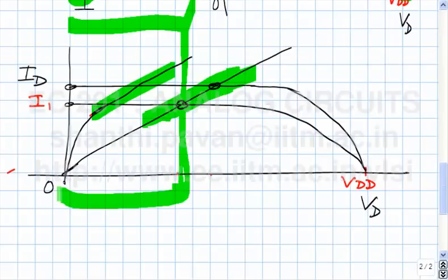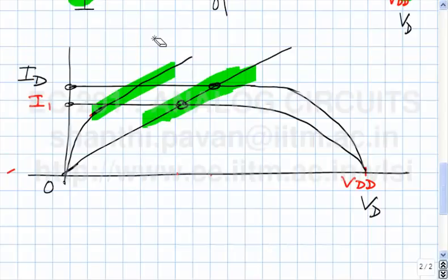And then you say, well, unfortunately, if this characteristic remained a straight line, then that element there would neither be linear nor passive. And then you say, okay, to hell with linearity, anyway we are only interested in incremental gain. Our MOSFET is so badly nonlinear to begin with, so it hardly makes sense to get hung up on a linear resistor. And then you say, well, if I wanted it to be passive, then the characteristic would be something like this, and it would eventually go into the third quadrant. So even though the slope was very small here, the slope should become larger and eventually go into the third quadrant. Does this make sense?